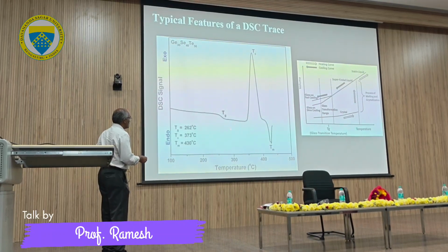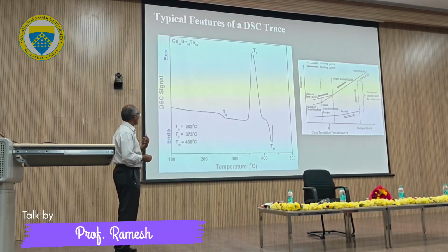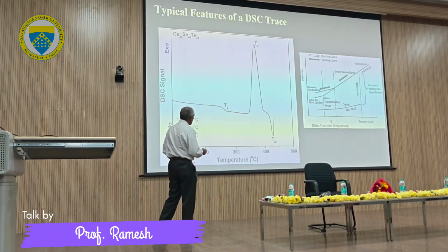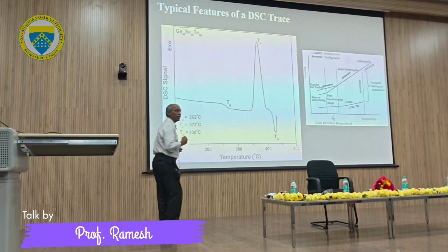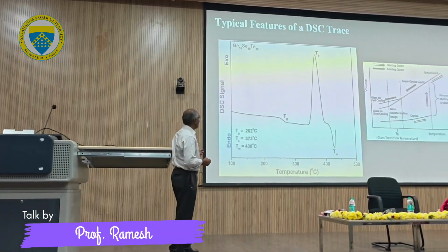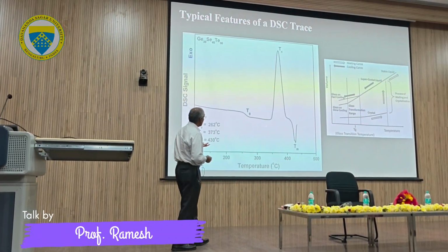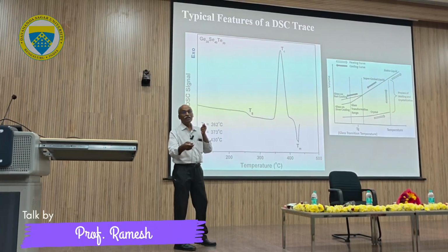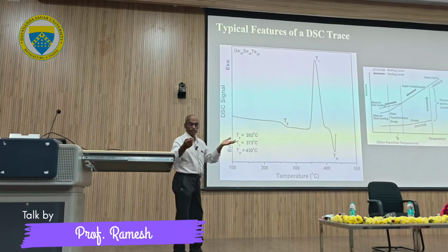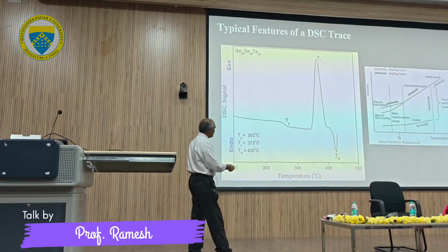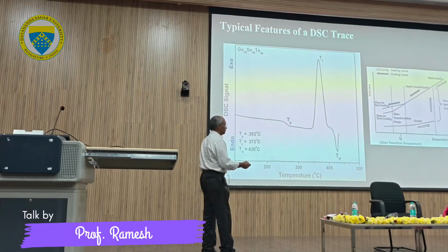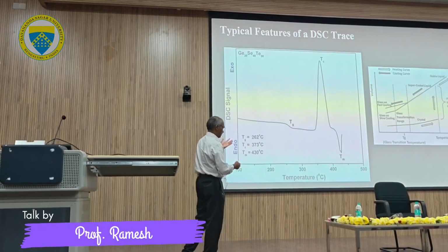They take the energy you supply, so this is an endothermic reaction, and if you keep heating, then it goes to the crystalline state. This is what is exploited in phase change materials. You give energy, and you can change the state from amorphous to the crystalline state. It goes to the crystalline state, gives away its excess energy and goes to the equilibrium state. With further heating, the bonds will break, and then you go to the melt state, right? That's what we saw from that figure previously.